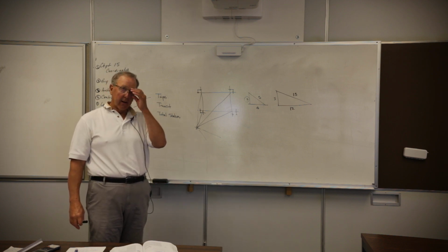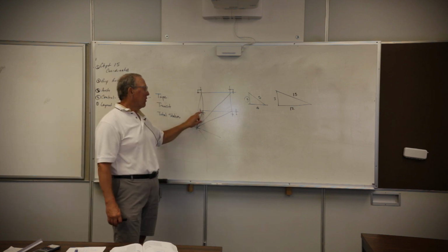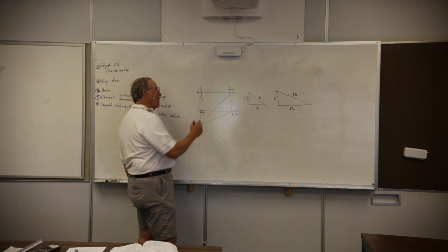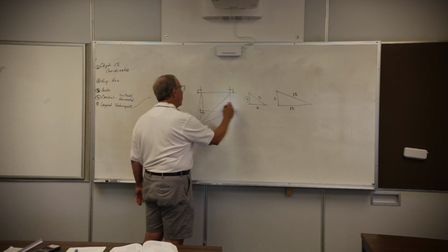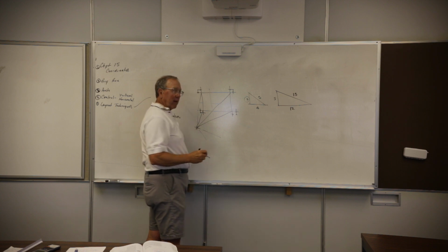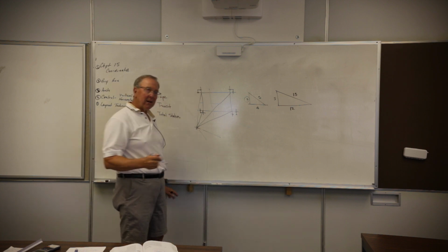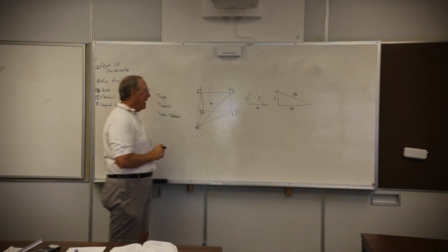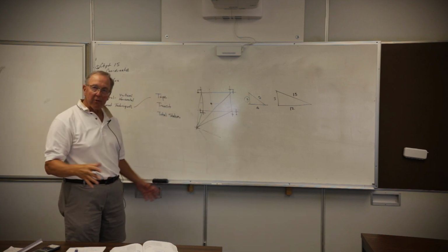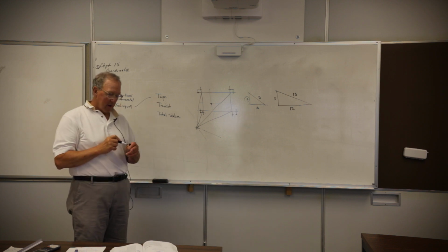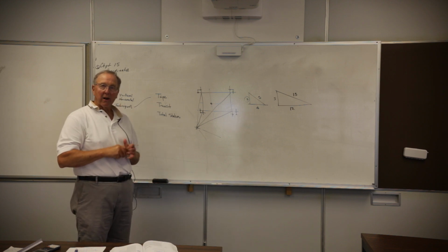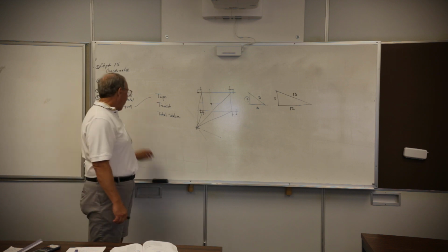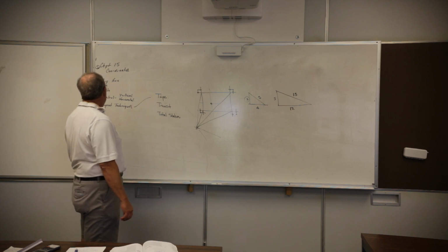If they don't understand it, older guys like these batter boards because they crisscross lines. Now they can set intermediate points and they can crisscross some lines. If I was to put a riser in for a plumbing fitting, they crisscross the lines, and right where those crisscross lines meet, they know right below that is where they're going to have this riser coming up. And then that should fall into the wall when the carpenters get there and frame around it. So that's the layout techniques, okay?